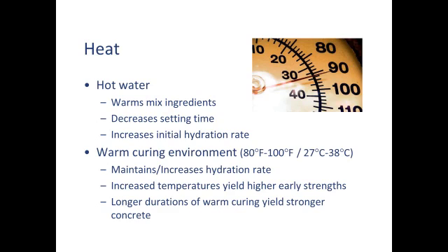Can I overheat concrete? Yes. You never want to get above 140 Fahrenheit. I don't know what that is in centigrade off the top of my head, but it's pretty hot. And you never want to get it hot fast. Commercial steam curing ramps up at a specific rate. You can Google that. They hold it at a given temperature, and then they let it cool down. If you heat up the concrete really fast and then cool it off really fast, you could shock it and actually cause cracks. So it has to be a gentle process, where you go from room temperature up to full temperature over maybe 8 hours or so. Gentle warming.